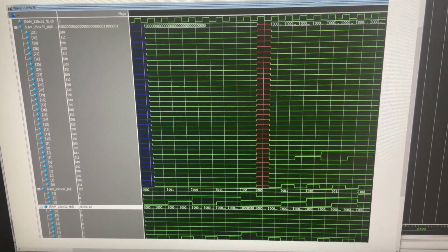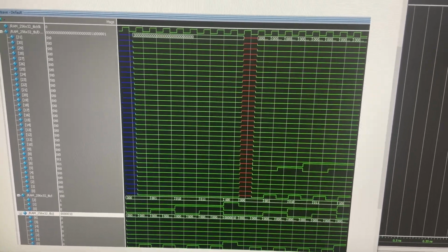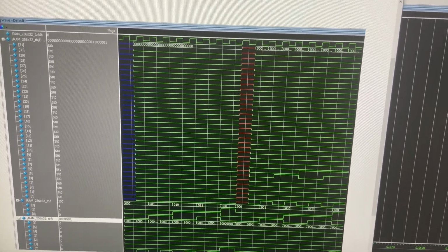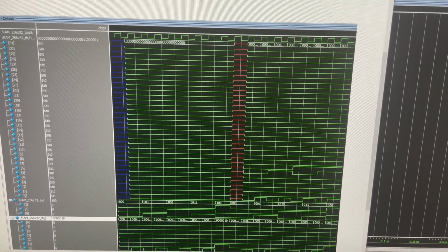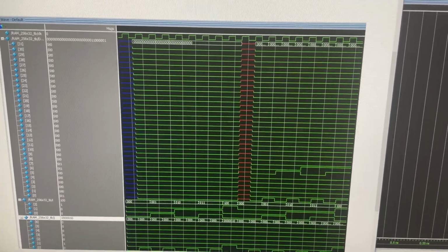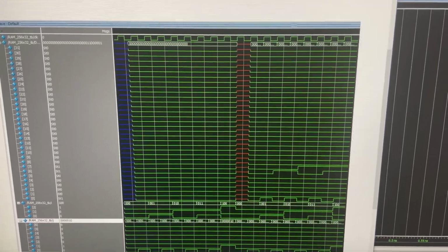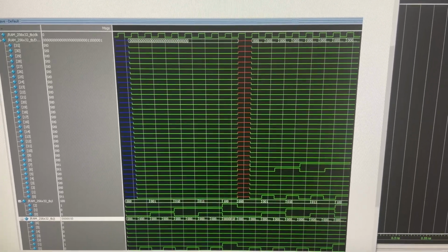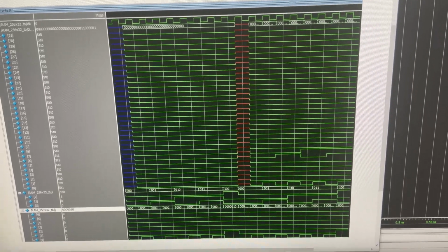So on the left side is the write portion of the 256 by 32-bit RAM, and for this part we are going to have a read write of 1, which means it's going to take an input and put the input into the RAM, which is shown on the left side. Each value in binary matches the data input value in binary. For each chip select in the RAM rows, like I said before there was 4, 1 in each row, we tested 2 addresses to show that the write part of the RAM works.